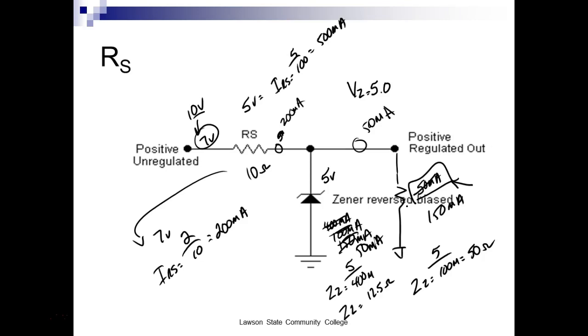Dynamically. So yeah, I could come up here and I could put this guy at 12 ohms, or I could put it at 50 ohms when the input voltage changes, but that input voltage is changing constantly, right? If the input voltage is the same and I've got a filter, then it's constantly changing. It's changing every 8.33 milliseconds, right, for a full wave. But the Zener automatically compensates for that, as long as I give it more input voltage than it's supposed to regulate. And we don't want to give it a lot, because if you do, then this power, this resistor, what